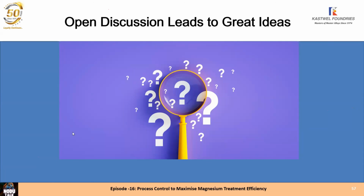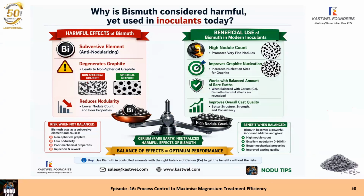I had some experience recently. I have a casting of 500 by 7 ductile iron in which the casting is reverse draft, so we have to use an outside core and an inside core for a center core, and we are pouring it through the center core from the bore of the casting, and both cores are painted with the graphite base GNX Foseco paint.